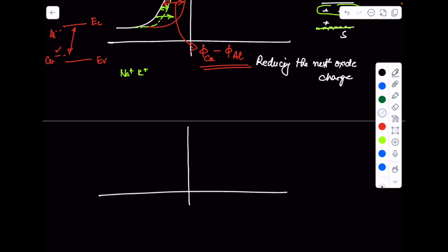Right? So we know that if the doping concentration increases, what's going to happen is, one, your VT is going to go up, two, your CFB is going to go up slightly because your phi MS is going to change, and three, your Cmin is also going to go up because you have higher doping, so the depletion width is minimum. So therefore you're going to have something which looks like this.